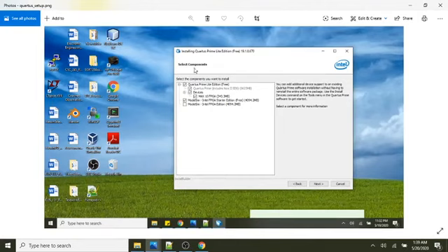you'll see it here when you start running to install the software. It's already got everything you need pre-checked. So it's got the Quartus Prime Lite edition checked. In this case, I installed a device, the MAX 10 FPGA, and then it's also got the ModelSim Starter Edition. So this is everything. You don't need this last one checked. You just want the Starter Edition for the ModelSim. So just make sure that you see all of these check marked here. And this is when you first run the install, when you double click on that executable file.